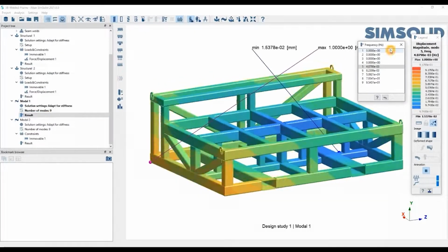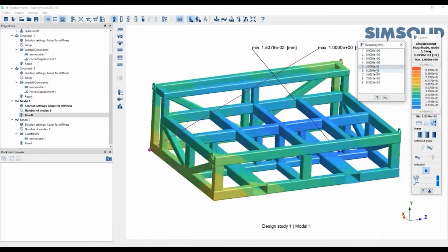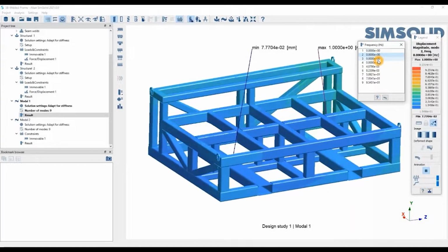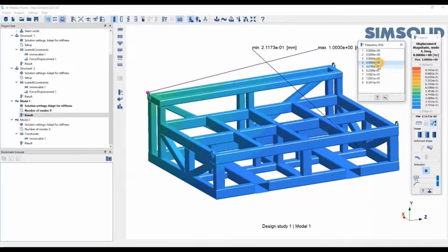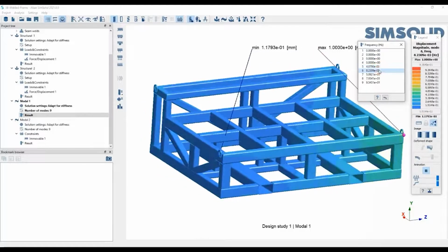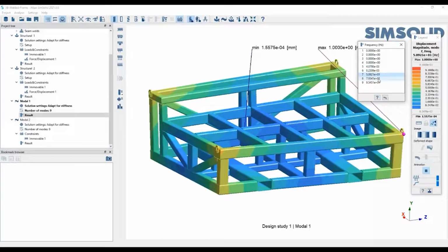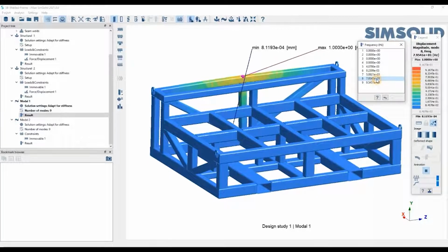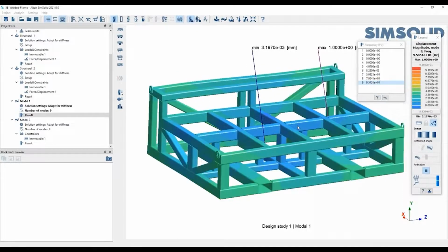With the modal analysis, like we can see here, the first 6 ones in our free analysis would be our rigid body modes, so how it would displace and rotate in degrees of freedom X, Y, and Z. And then when we go through to start looking at its actual natural frequencies, you can see whether you have your bending modes or if you have any torsional modes instead.